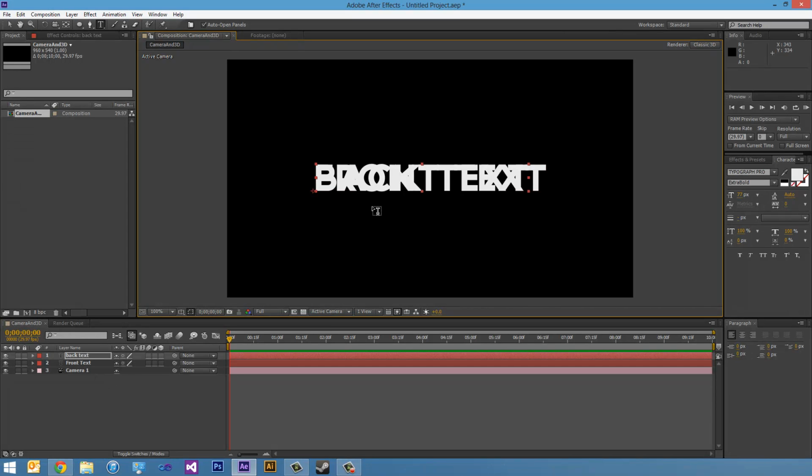So right now these are 2D layers. I'm going to modify both layers, front text and back text, to be 3D. To do that, depending on your modes here, click this little toggle switches / modes button until you see what looks like a little 3D cube. Once you see that, check that box in both layers. Now they are both 3D layers.